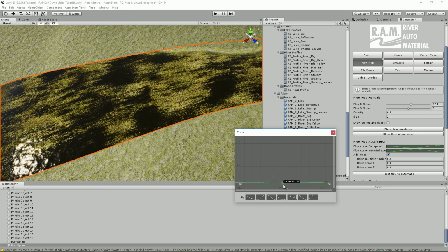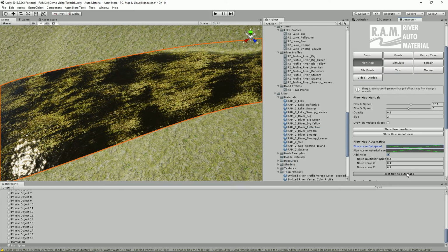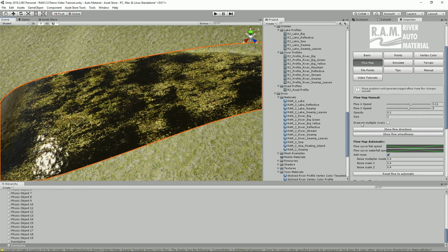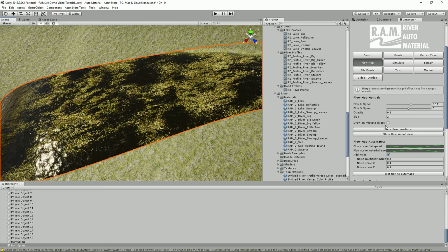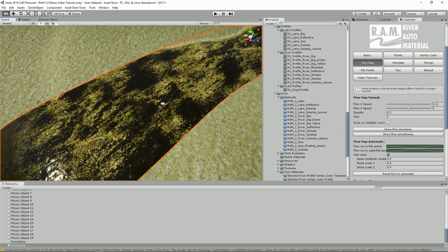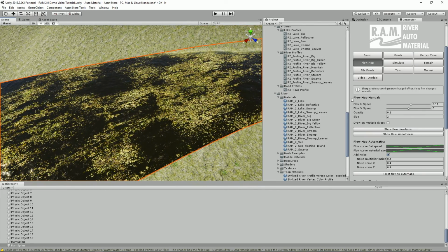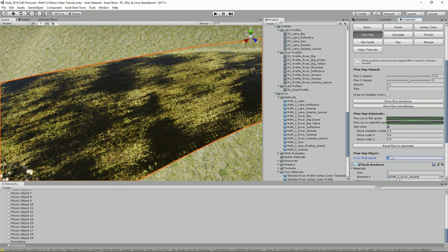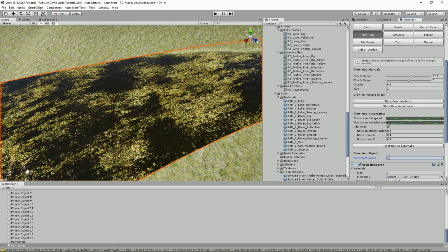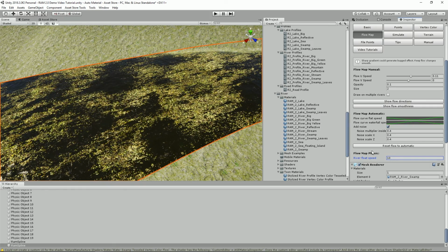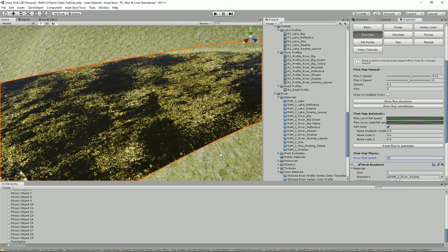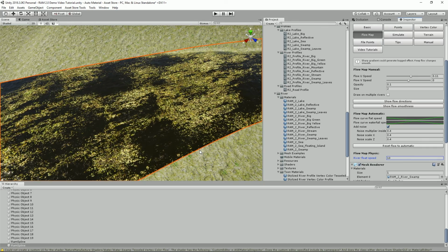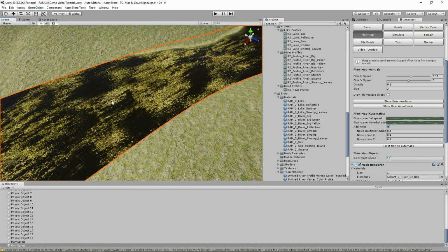There is another thing that should be very interesting in Flowmap, because there's a connection between Flowmap and physics. We set a value which is called Flowmap physics, and it's the connection between water mass and physical power which affects the colliders and objects which flow on the water surface. We advise you to use value equal to 10. It's a basic value. The rest could be adjusted by colliders and rigid body and buoyancy script.